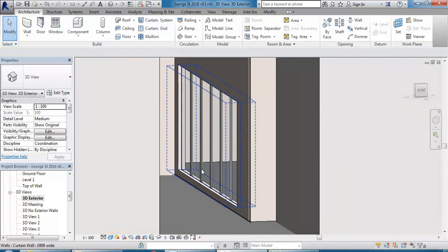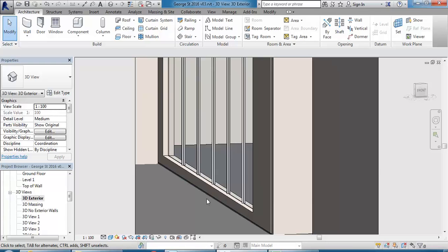Can you see how much easier that is than trying to make a window with those properties? And people often go searching. I see people looking for fixed windows that have a certain number of panels and all the different options they want, when a curtain wall is usually going to give them everything much more easily, and you can fine-tune it if you decide that you want to put in a grid pattern.